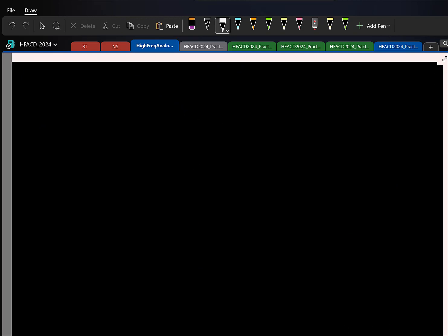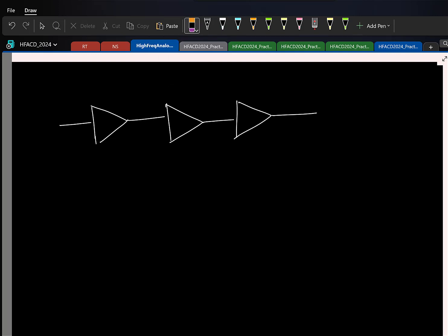can be extended further. So let us say I have a 3-stage amplifier. I'll draw it with triangles now for simplicity. Again, for each stage, I know the input referred noise that you, let us say, calculated already. Say it is Vn1, Vn2 and Vn3.